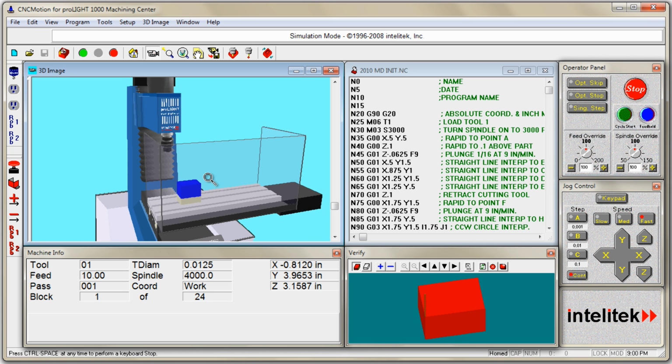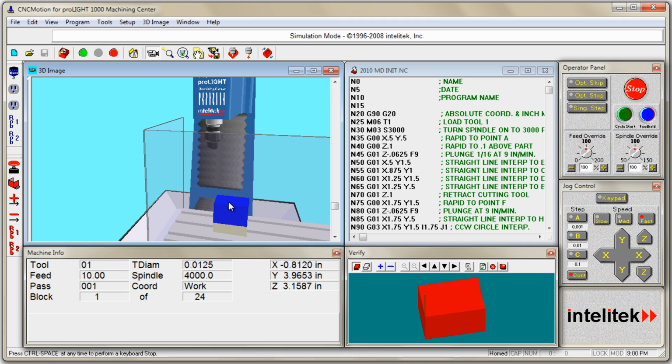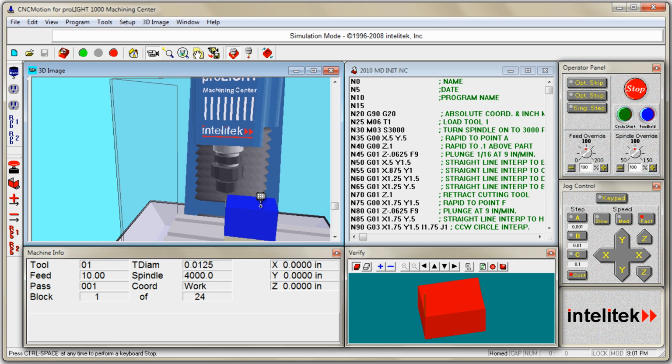The next thing you have to do is tell it where the block of material is inside the mill. To do that, we have to find PRZ, or the corner of the block, which is right there. It's very easy in simulation. You choose the tool, Send Tool to Corner. If you click on that and then click on the front left corner, it'll send the tool to that corner.